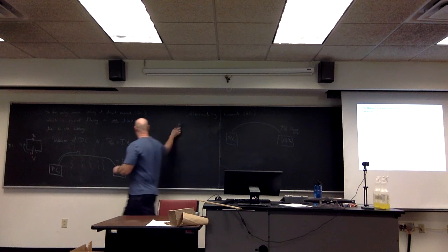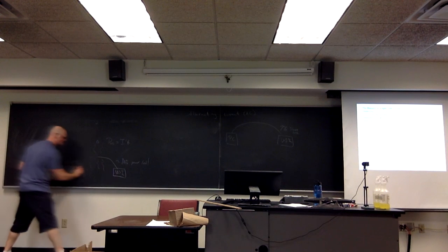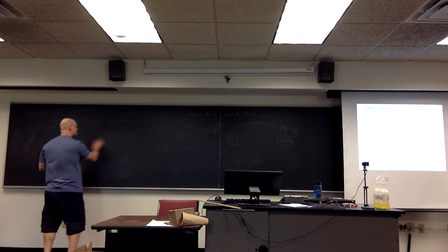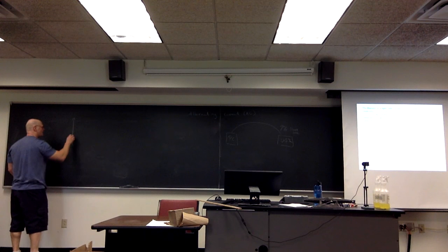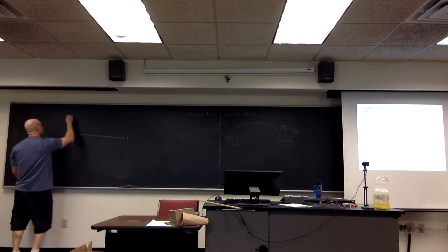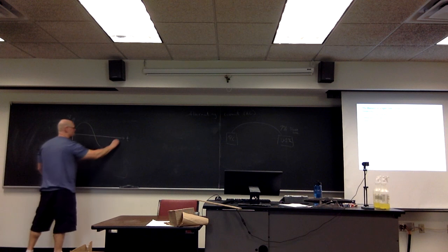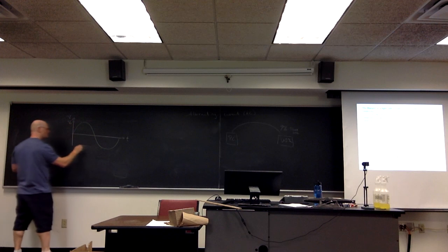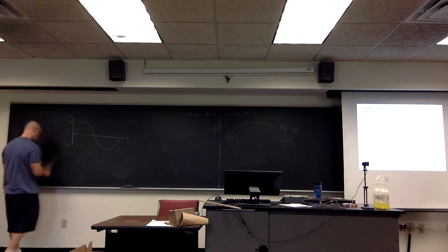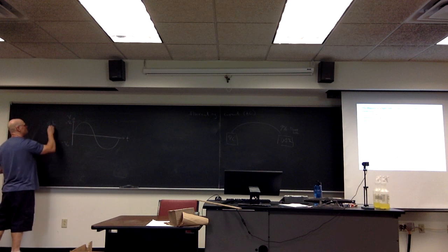So what then are AC currents? The way we create AC currents, and we'll talk more in depth about how this works later when we start getting into magnetism, is that your power company creates a sinusoidal potential source. If I was looking at the potential as a function of time, this would go as a sine curve, going up to some maximum amount of potential, which we call V0, down to some minimum amount of potential, which is negative V0, where V0 is known as the peak potential.